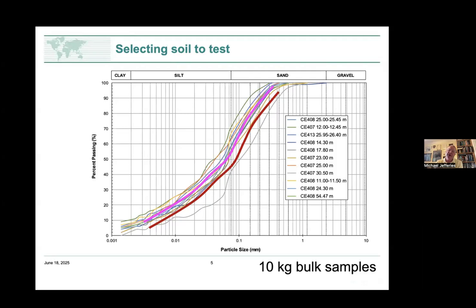We're trying to look at the effect of slight changes in gradation on the properties. For example, as you go coarser, which is the brown line, you'll find the slope of the critical state locus changes a little bit. So we're trying to assess the effect of our material type change on our behavior.